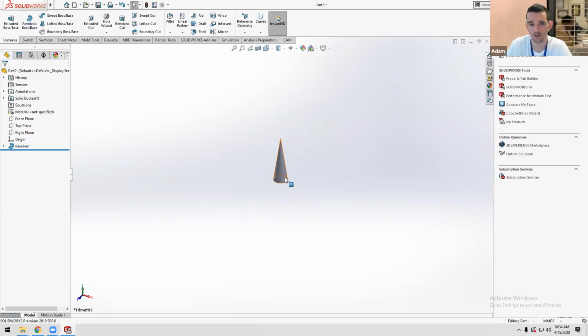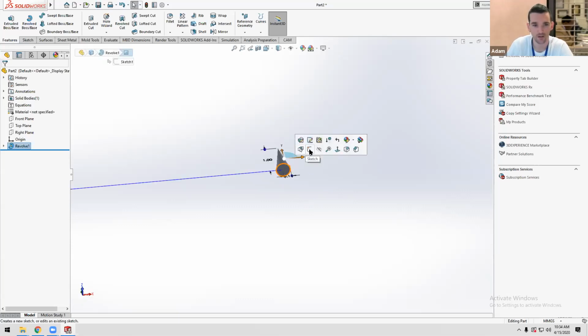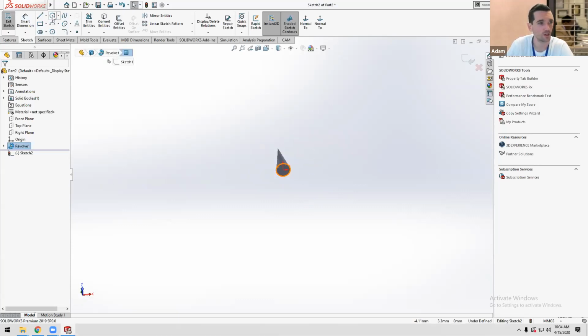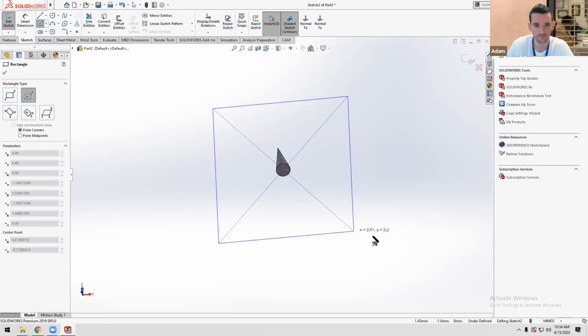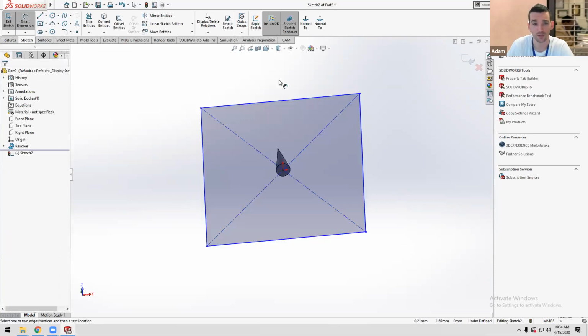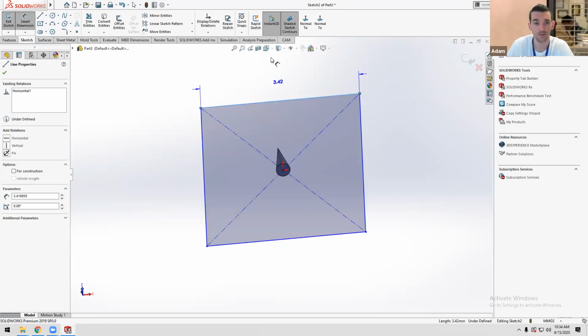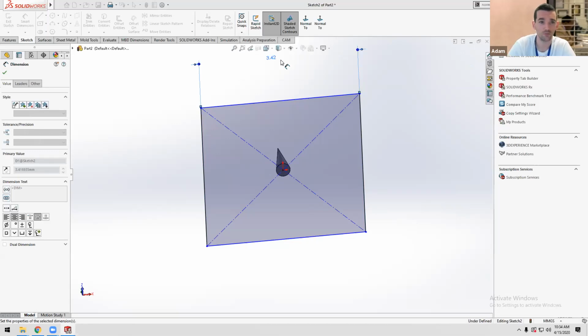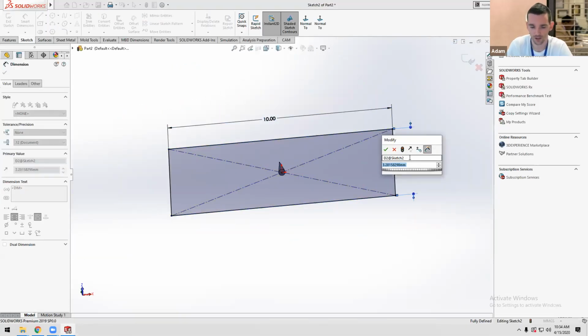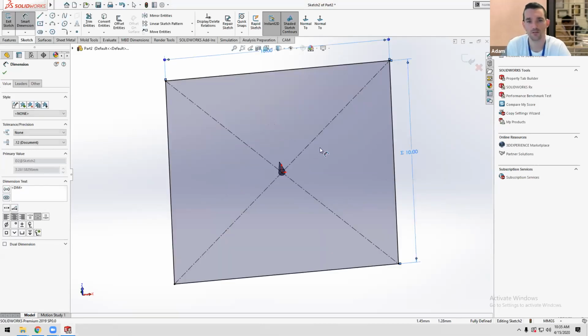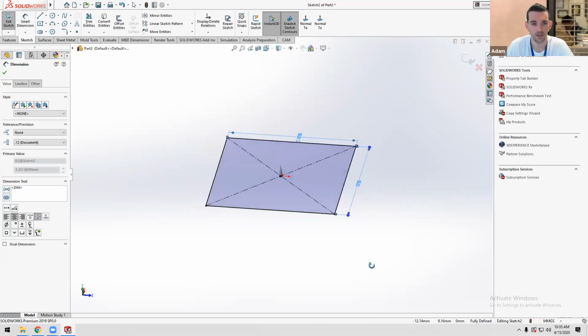And now, let's say that's the center of my patch. I need to make the base of the patch underneath it. So I'm going to sketch on the flat surface on the bottom. And I'm going to define a dimension of the patch. Maybe it's a rectangle. And this rectangle is a centimeter, so that's going to be 10 by 10. If I want to make it always square, I can just make this dimension equal. Enter, enter. Okay. Now I've got a sketch.